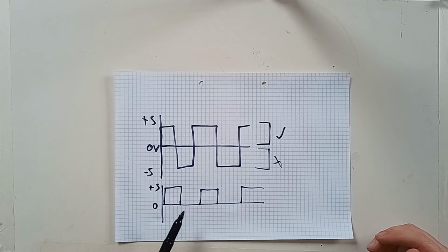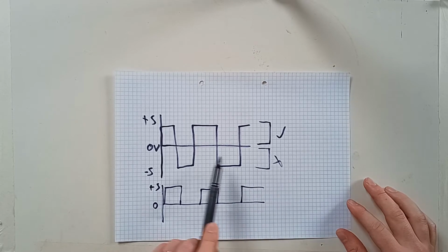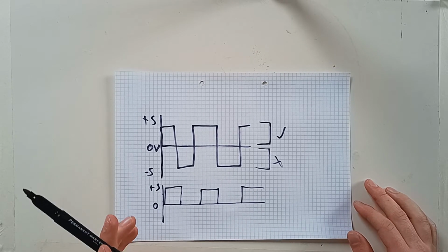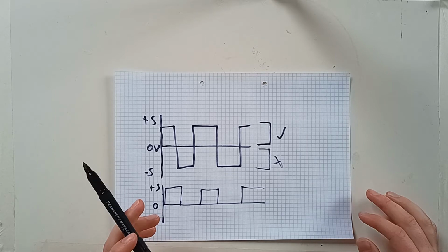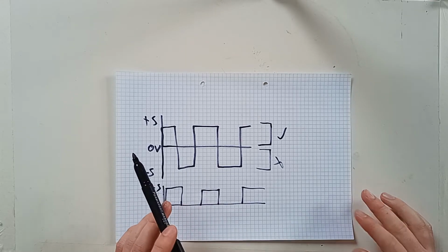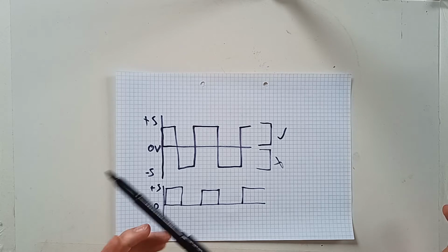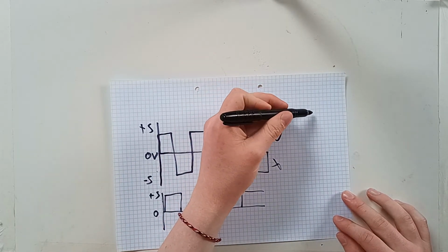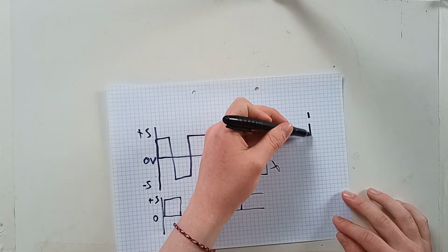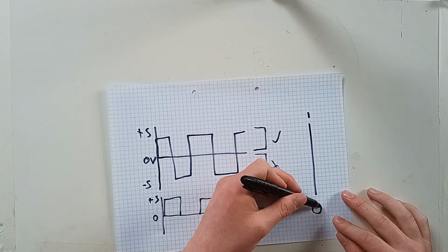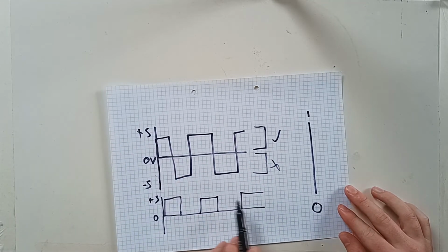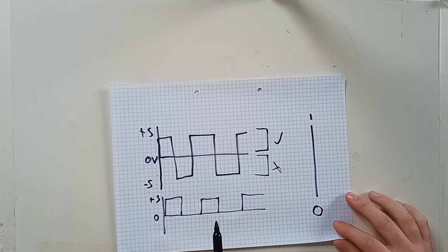So in order to make it so we can pass our whole signal through the actual diode ladder, we need to adjust how it is being connected, because if we just had the input at the top of the ladder going through it all down to then ground at the bottom, we would only be getting this top half. So we have to bias it.